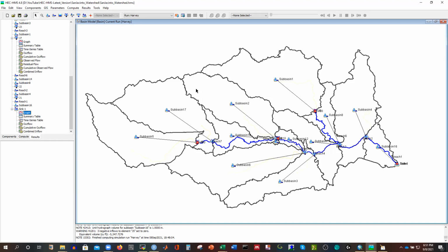I'll use the standard hydrologic grid, and I'll show you how to create the gridded precipitation. If your model is gridded, then you have to create the gridded precipitation. I'll also run the model for a long time, like 20 or 30 years or 25 years. Then I'll use a different loss method, the soil moisture accounting method. Okay, and then I'll show you how to estimate those parameters. For that SMA we need temperature, and I'll use Penman-Monteith for evapotranspiration. So I'll show you how to calculate relative humidity, because it needs relative humidity, pressure, temperature, and shortwave radiation, longwave radiation, everything I'll show you. I already downloaded these variables. That's why when I was downloading this netCDF file from NLDAS, I selected everything. We have every variable there, so our data is already available. We have the data, so we can process that when I run it.